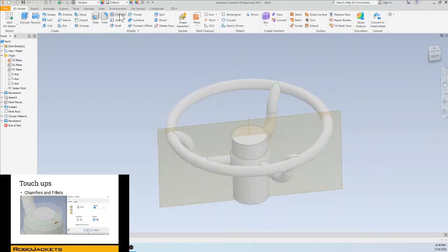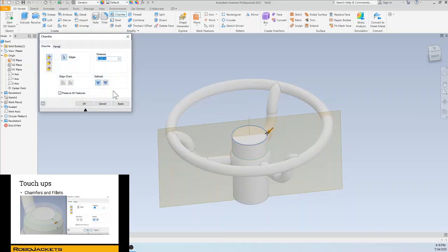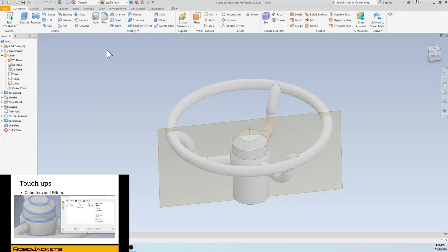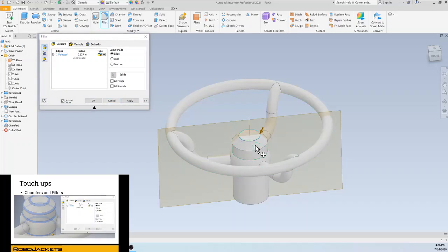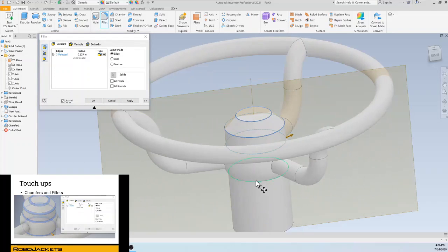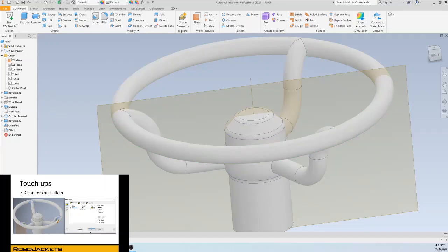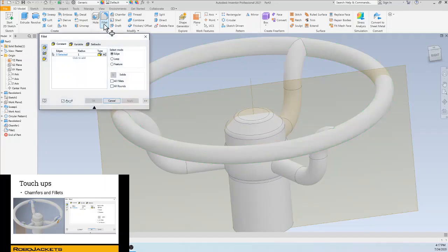We're going to make some chamfers here, and we're going to pick the just general distance chamfer and make it a distance of 2 inches. And then we'll create some fillets to round it out real nice. And that will be a distance of 1 inch. And then we'll do some more fillets.